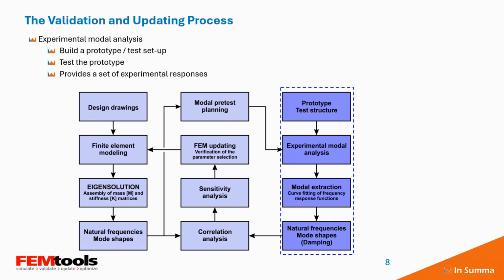And then from there, we can do all types of model extraction as well. So we can have accelerometers to measure the accelerance of the model, and then we also derive the natural frequencies, mode shapes, and other parameters specific to the test model in this case.